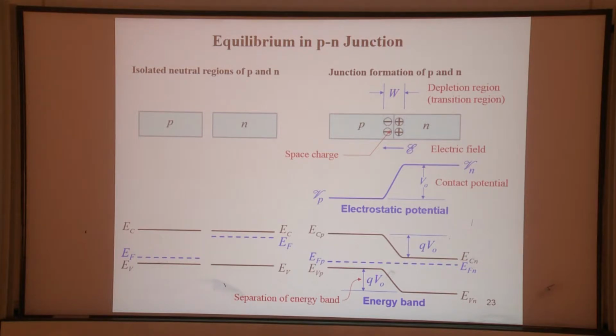If we increase the doping of P-type and N-type, the electric potential will be increased. Increase the doping, yes, and the electric field increases until the limit where it stops. The potential is a function of doping as well as band gap, and of the doping difference between the two sides. So that is a little bit complicated equation.